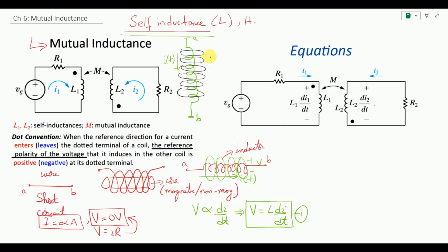Normally, as we studied in our initial lectures, whenever we talk about circuit elements, we do not consider the portions inside the element, rather we consider them to be lumped elements. By lumped elements, we mean that instantaneously the same effect is observed from point A to point B. This is what we call lumped behavior. So rather than analyzing each magnetic field inside each turn of the coil, we consider that the effect is instantaneously spread over all of the inductor. Whenever a changing current I of t is moving through a conductor, it is going to produce a magnetic field.